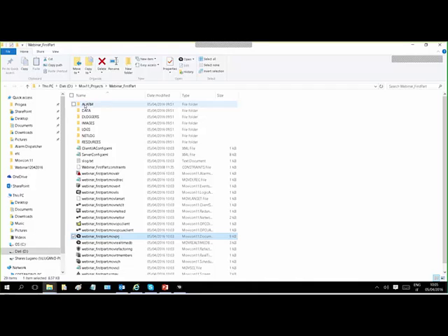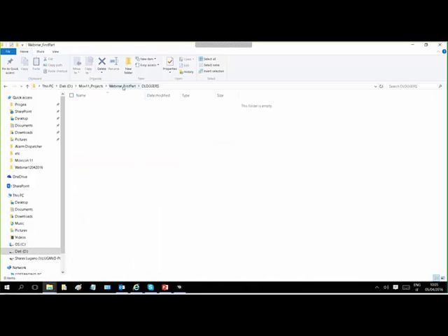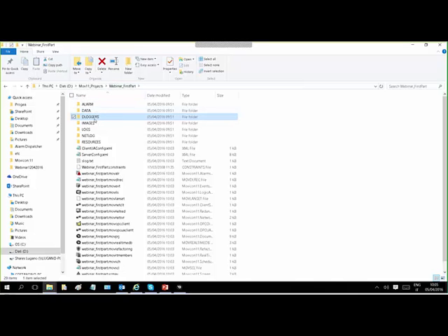In the folder, we have information regarding the alarms, information regarding the variables, in case you are using the data log resource, so you are storing your field variables in the database. Here you have, for example, the HTML files where you keep the reports, in case you are generating a report of the data. Images, JPEG and bitmap, that you are using are stored here, so you can easily make a full backup without caring about the link of the image.